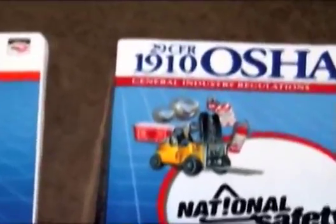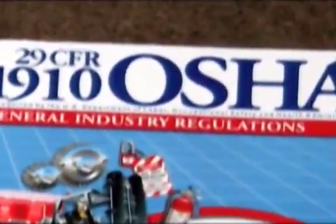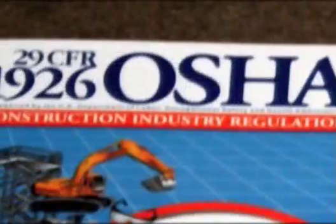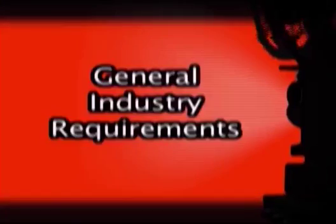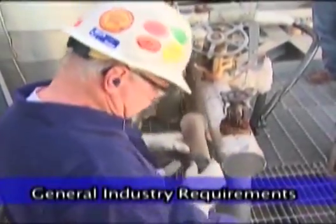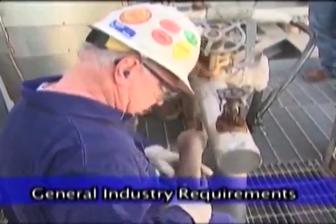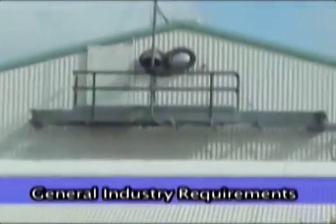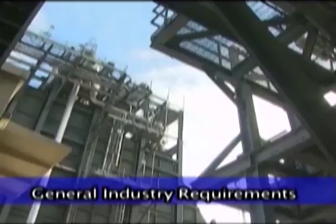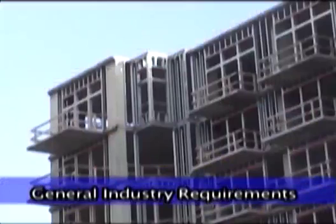This program will highlight CFR 1910 Subpart D for general industry and CFR 1926 Subpart M for the construction industry. Anytime an employee is working 4 feet above a lower level, fall protection must be provided. The 4-foot rule applies, but is not limited to open-sided floors or platforms, runways, wall openings.